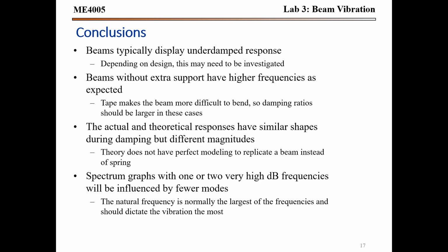And so in conclusion, the beams will display underdamped responses since it is modeled after a spring system. And depending on the design, this may need to be investigated, whether you want the beam to be critically damped or overdamped. This might need to be changed. And beams without extra support will have higher frequencies, which is expected since the tape makes the beams more difficult to